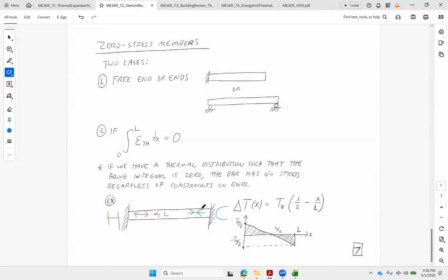All right, did anybody have any questions about the basic thermal expansion? How we set it up? It's always the same on strain, alpha delta T. And then how we go up to displacement, whether it's constant or a function for delta T.